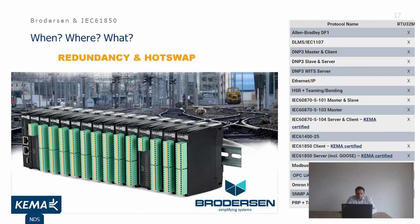The RTU is designed to be installed in harsh environments, has coated print, high isolation on I/O modules, etc. But one of the most important is the scalability of the RTU. It can be a low I/O count up to a really big system with redundant power supplies, redundant CPUs, and redundant I/O modules, for example, in SIL.